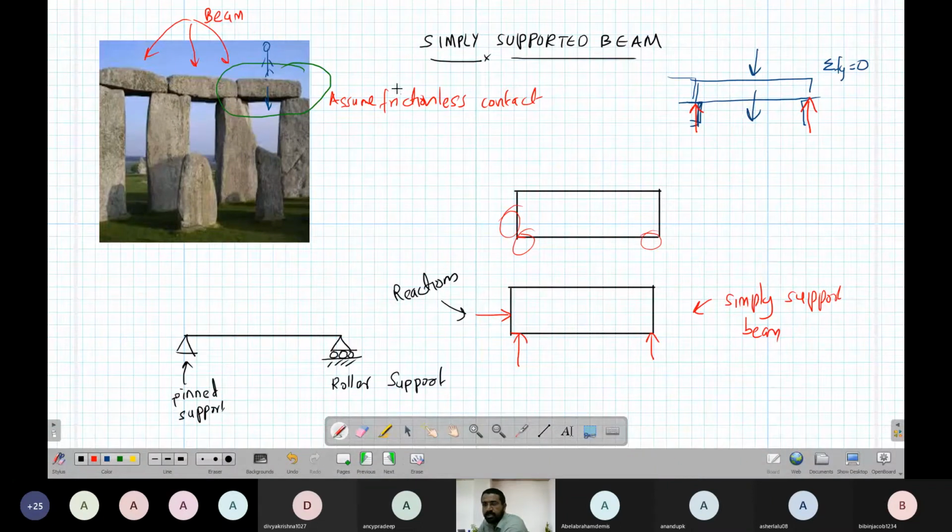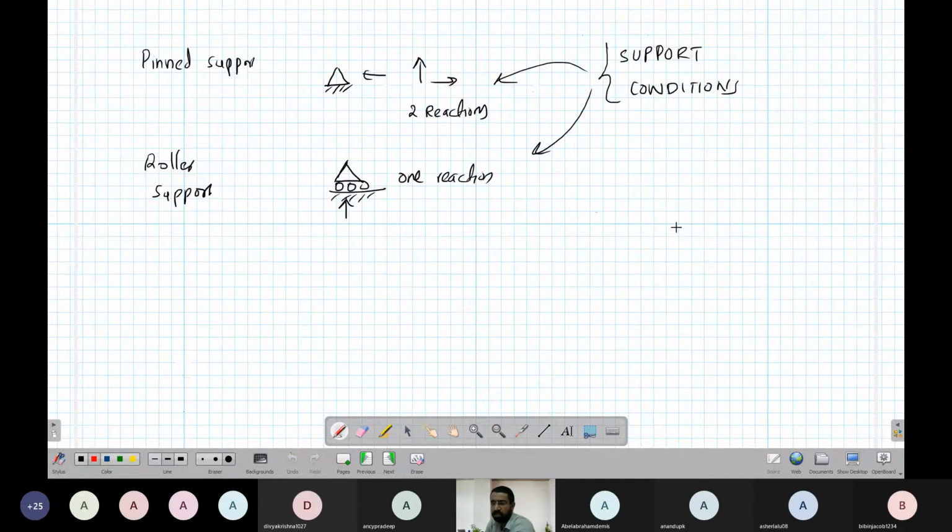So this kind of arrangement is what is known as a simply supported beam. We practically use beams, and that is why we have to find this. Why are we finding this? There are many reasons. Let's say the weight here is not a person but a huge weight. If this stone is not able to give that much reaction, it will break and come down. So we have to see what force is coming on this stone, to make sure the stone is strong enough to stay in place. We have to evaluate this force. Now we will elaborate more on this.